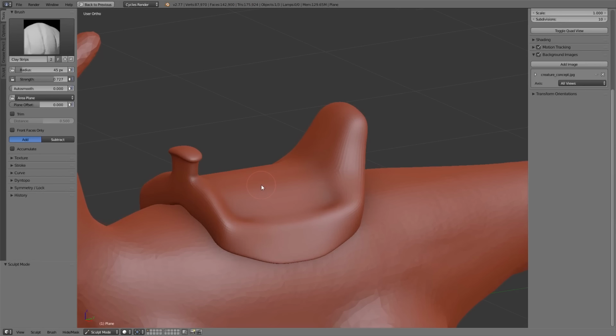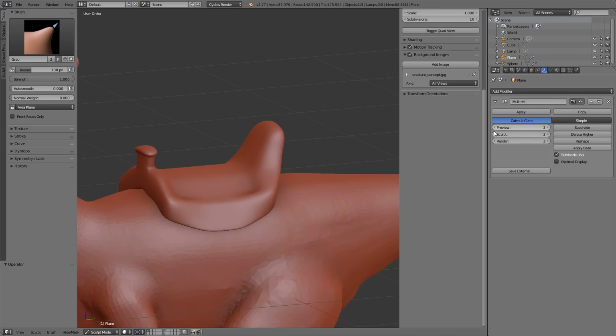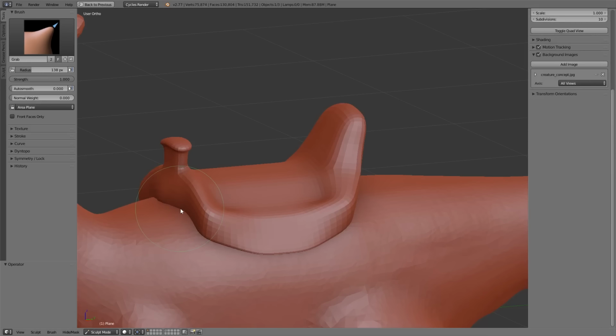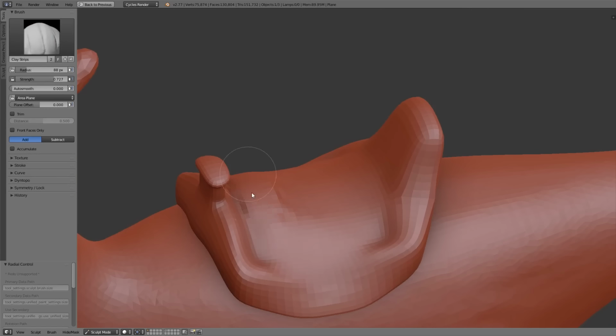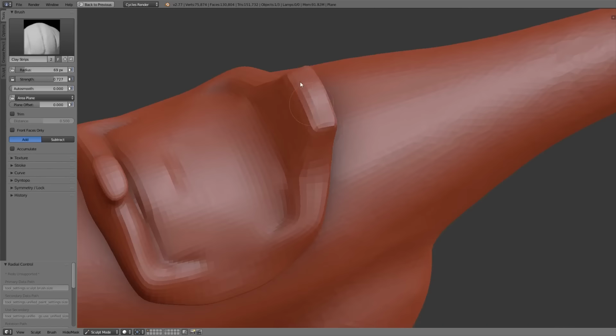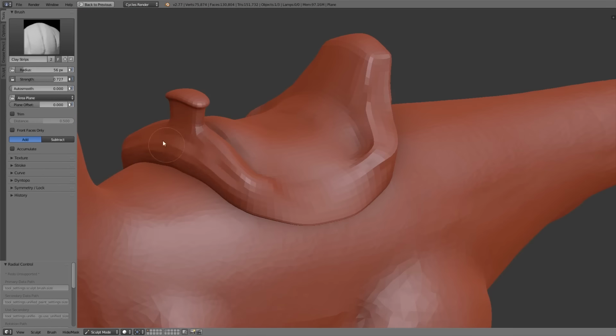The only difference is that this modifier stores the sculpting steps. That means every time I could lower the steps, sculpt in a rougher subdivision, and after that I can increase the subdivisions and still all the sculpting strokes remain, no matter on which of these detail levels you sculpt. That means in this way we are quite flexible with this modifier.